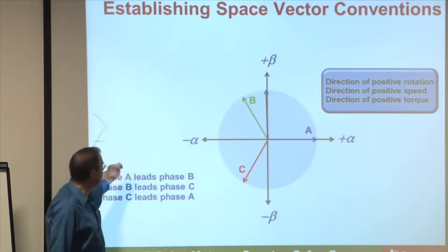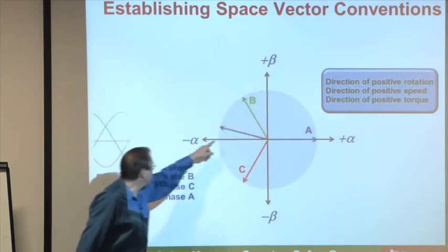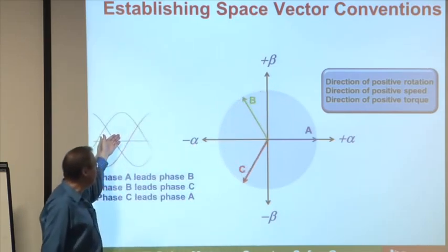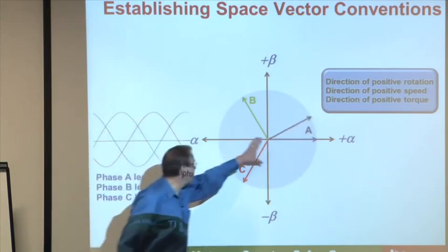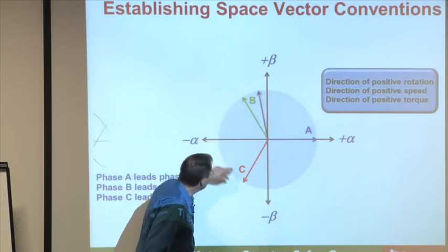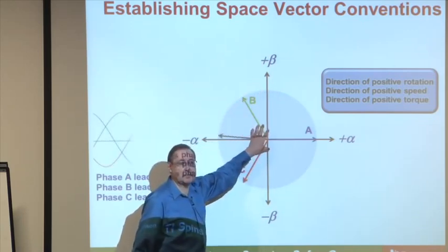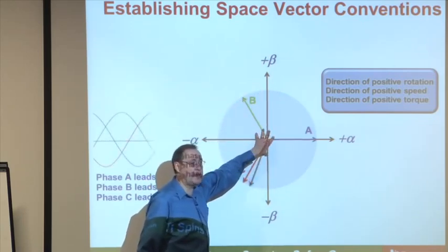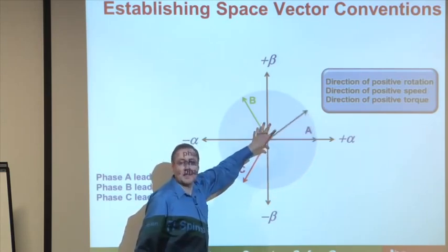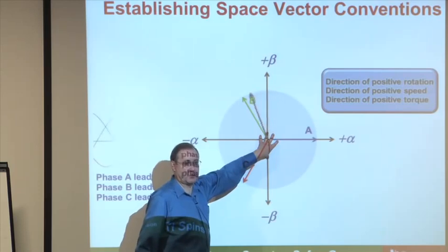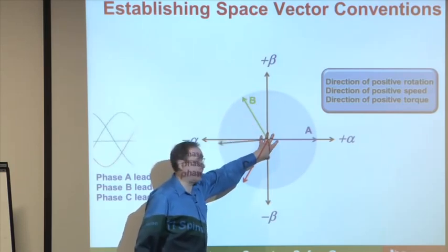Again, you can see this in such a way that the rotating vector, now this could be voltage, it could be current, it could be flux, whatever, we're going to represent all those vectors on the space vector diagram. Keep in mind, this is spatial representation with respect to the motor's cross-section. This is not phasor representation. This is spatial representation, which is why it's called space vector representation.